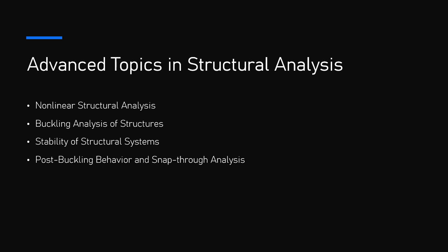2. Inelastic buckling. Inelastic buckling occurs when the structure has already undergone some plastic deformation before buckling, often in materials like steel or concrete. The structure may undergo plastic yielding before buckling and could continue to deform after reaching the critical load, unlike elastic buckling where the deformation is limited. 3.